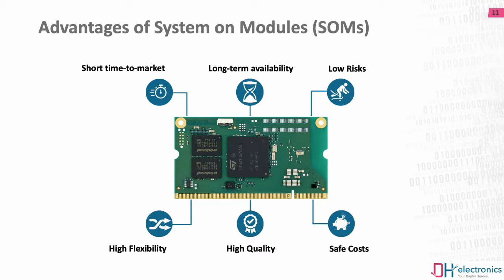And finally, our DHCOM SOMs are sharing the family design, which means that they are interchangeable. So maybe once you've designed your hardware and it is running fine for a few years, you might reach a point on which you want to add some more software features, but then you realize that your SOM is not powerful enough anymore. In that case, you can just pick up a new DHCOM module and populate it on the same baseboard, and therefore you can increase the capabilities of your product without the need of a huge redesign.